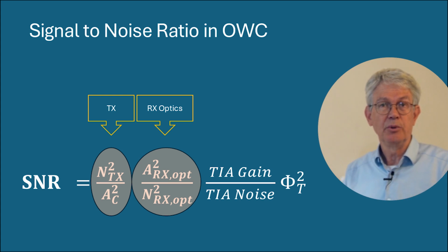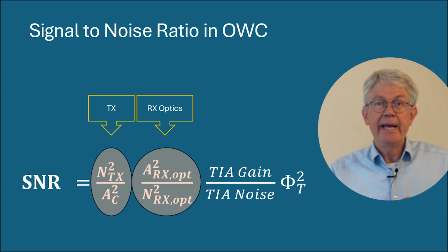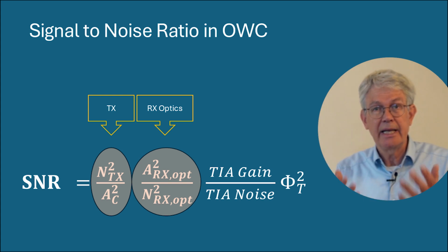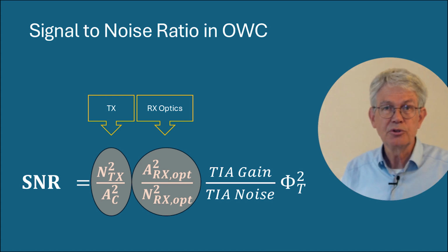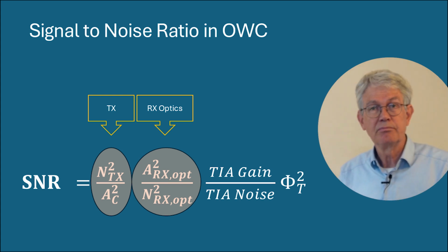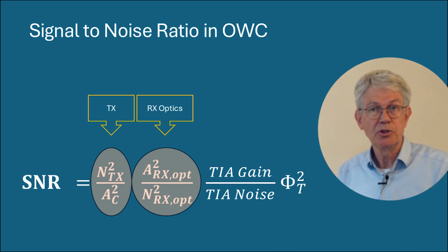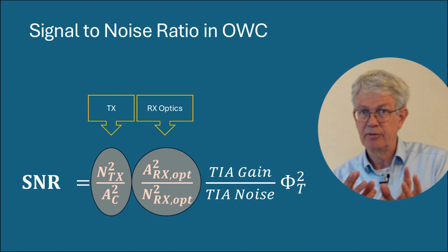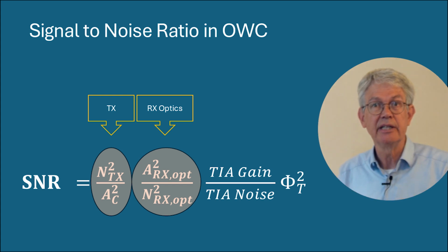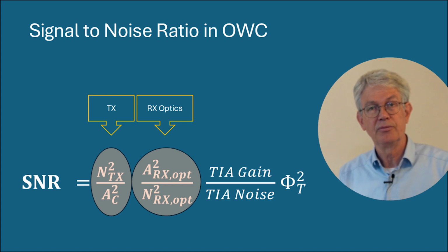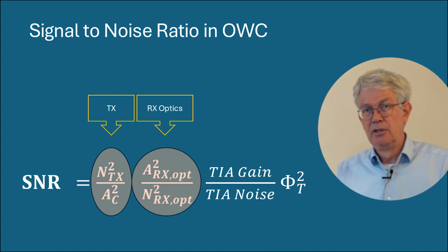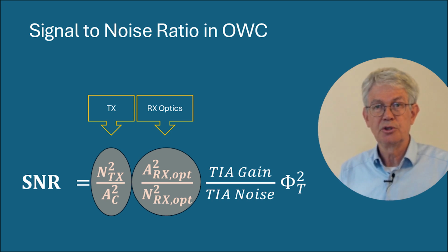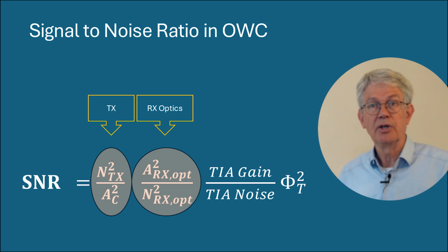In the receiver, it works differently. I like to make the area of the detector, the optical size of the lens, as large as possible, because then I can collect many photons. Many photons means that the current is proportional to the area and the signal to noise ratio proportional to the square of that area. But if I start to split the lens by having many tiny collimators like the insect eye has, then I have to divide by the number of detectors there. So sectorizing at the receiver may not be very helpful. But if we do that in the non-imaging way.